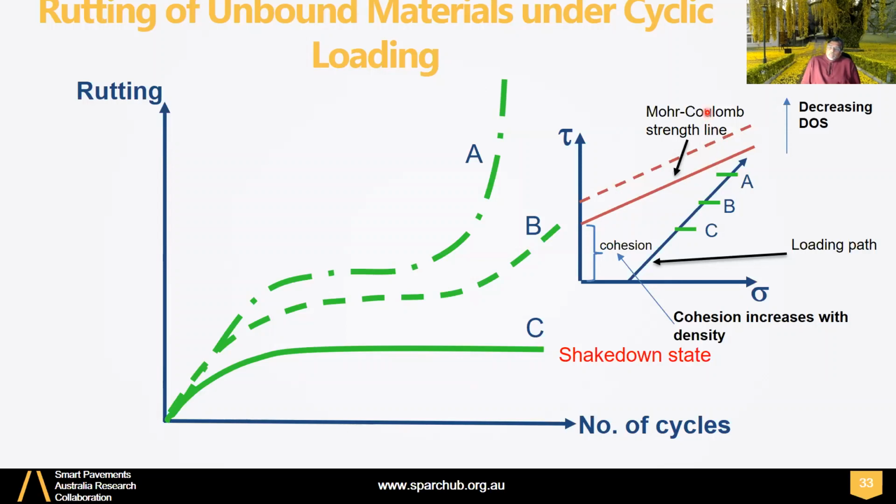How can it be far away? Gradient is the friction angle, which is based on material. So 40 to 50 doesn't change a lot. Whereas cohesion is based on the density, how much void ratio you have achieved. So higher the density, this line will shift up. In addition, where's the moisture effect coming?